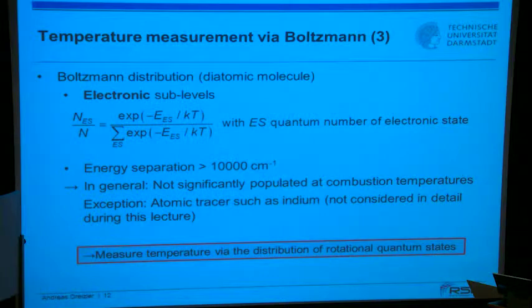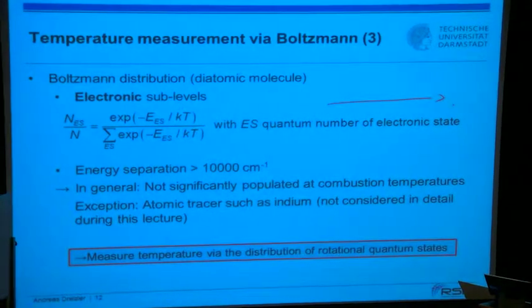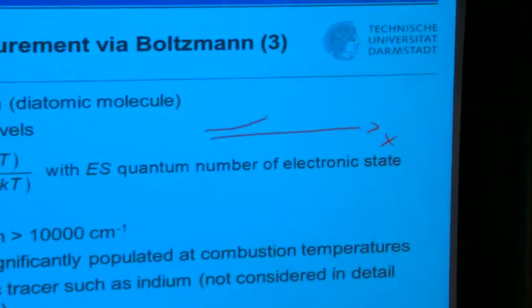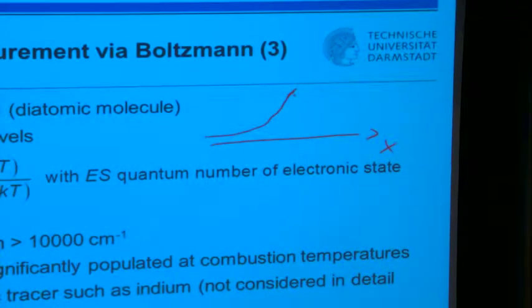That is maybe a side remark. So based on that explanation, maybe it becomes clear why, for example, CH star chemiluminescence is good to monitor a heat release zone. CH star would not be excited through temperature. If you have, let's say, the post-flame region, and maybe I should make a drawing. Maybe if you have here a space coordinate, and here, for example, the temperature going from ambient